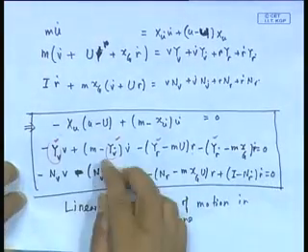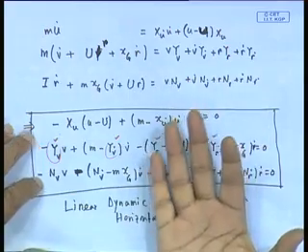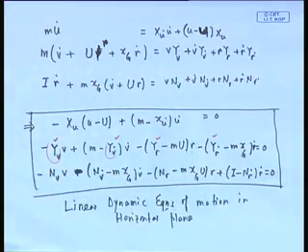I will again discuss that. You will understand that this part is nothing but minus of added mass. We are just writing them in a different equation. There I said m plus added mass into acceleration. Here I am saying m plus minus Yv dot into acceleration. Obviously minus Yv dot is nothing but added mass. Now added mass is a property of the hull. For a given hull there is an added mass. What is added mass?